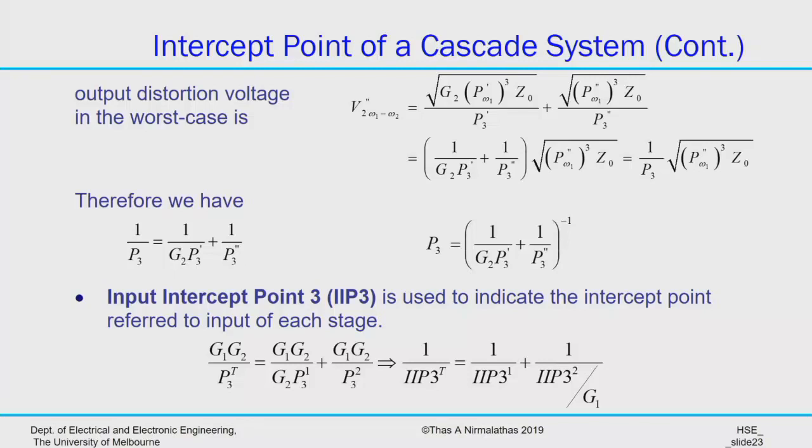Essentially what we're doing is just taking those intercept points, as I tried to do over there for a third order term, looking at the amplitudes and then working out what the final P3 will be, and then realizing that it is in this form, and that's what I've just done. This is IP3, and then IP3 divided by a gain. So that's what I've done there.